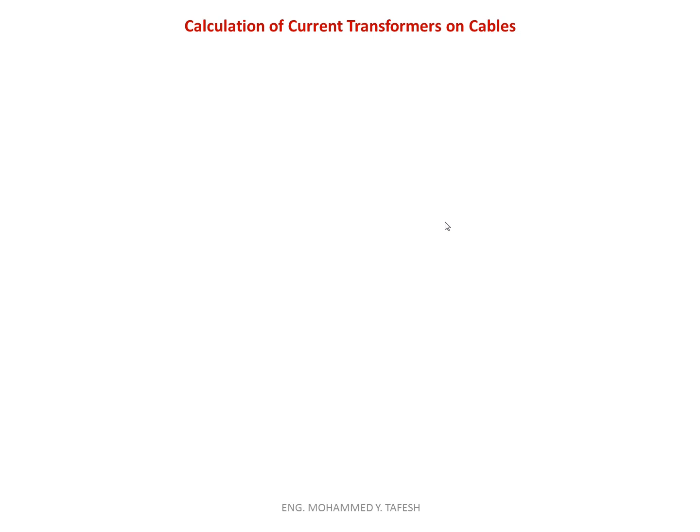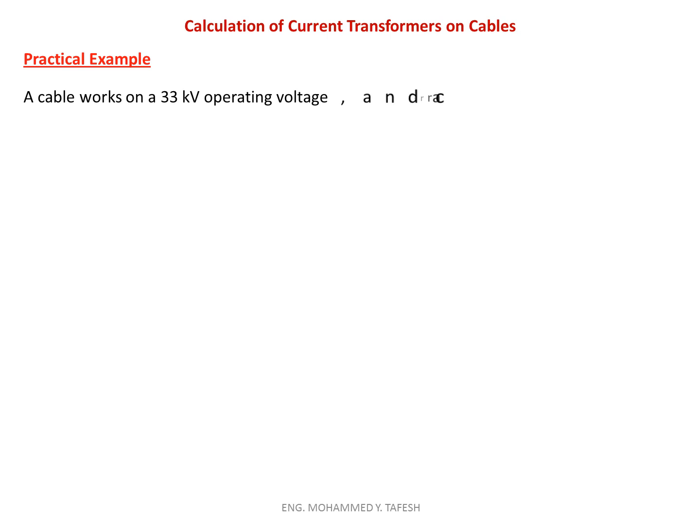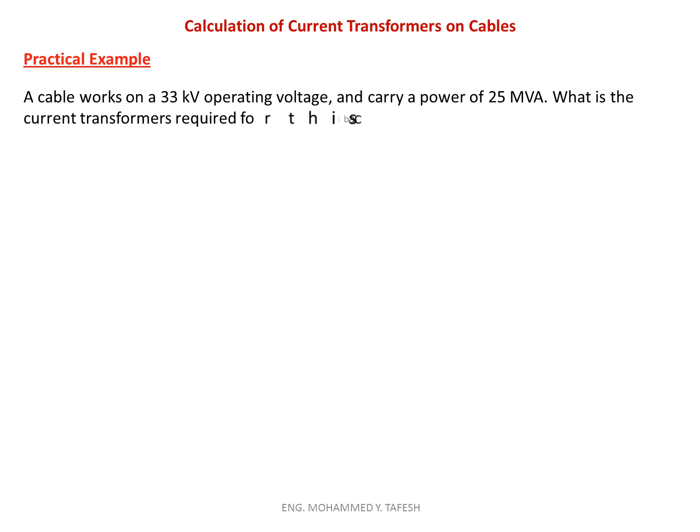Now let's do some important calculations of current transformers. First case on the cables. Practical example. A cable works on a 33 kilovolt operating voltage and carries a power of 25 megavolt ampere. What's the current transformer required for this cable?